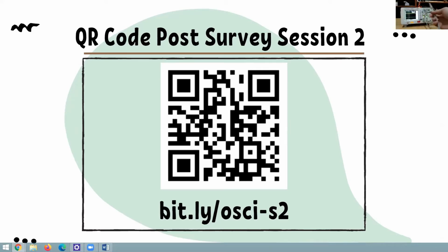So I have the battery here. It's a 9-volt battery. You can use this under this. This is the yellow. First of all, is for measurement of DC or AC. If you want to measure a DC value, we have to change it to DC coupling. All right, so you have DC coupling. Let me remove this number 2. You can actually measure DC, making sure that your voltage scale is correct.